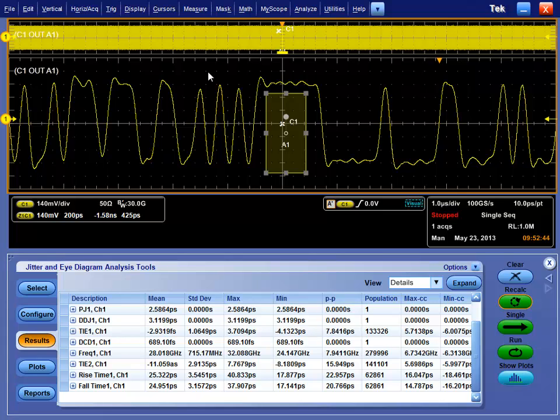If you're going to debug, a real-time scope is often better than a sampling scope, and even at 28 gigabits, the Tektronix 33 gigahertz real-time scope has plenty of horsepower to deal with your 28 gigabit signals in those ranges, as you can see from everything we've looked at so far.